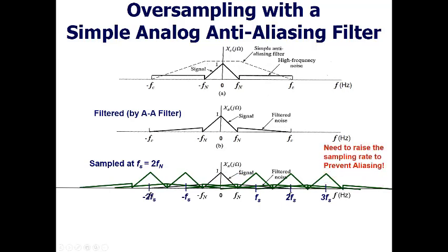And down here in our range of frequencies that we're going to keep, we have a lot of aliasing going on from that noise signal that wasn't eliminated by the anti-aliasing filter. So that's not going to be satisfactory. This filter wasn't good enough to use just the basic Nyquist rate sampling for our original signal.